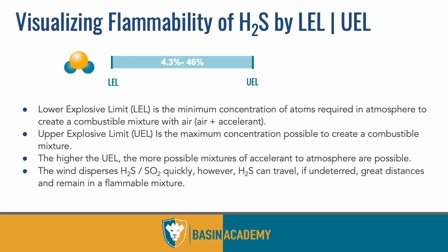So the problem with this range here being trusted is, just like a campfire, concentrations of gas move very similarly through the air in clouds and whiffs and in wispy ways. Unless you're enclosed, in one area you may be in a highly concentrated area, and then the wind direction shifts, or because it's heavier than air, it changes its own cloud formation by its own vapor density. It can be another concentration somewhere else quickly.